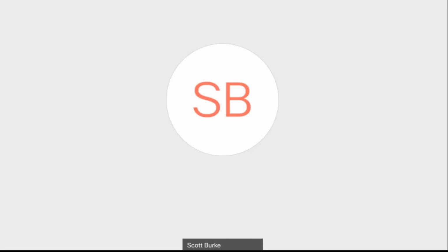Your administrator actually has to turn this feature on inside of the BIM 360 project administration area. There's a place where you turn on allowing people to share external links. And then you can send a link via email to a non-licensed user of the software, and they can absolutely download the file. Again, it does not let them into the system. What it does do, though, is allow them to download any file that you would like to share with someone. So it's a little bit like Dropbox, where you have to own a subscription to Dropbox, but you can absolutely share a file with people outside your system that don't even have a license. They don't even need an Autodesk ID or anything. They can absolutely access that file.